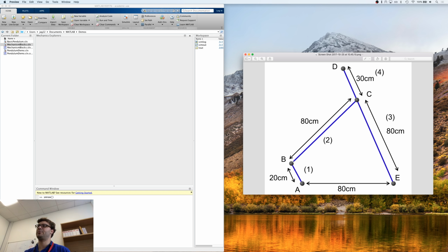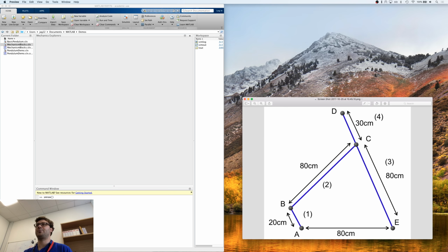So what I'd recommend is, once we follow this demo, you want to be able to make your mechanism of your convertible roof, with all the beams in the right configuration and places. Look at creating your motor and gearbox feedback loop using a single mass and pendulum. Once you've got that feedback loop and you're happy with it, you will then be able to import that and add that to your mechanism system. It's good to try and keep them separate until you're happy with both, and then bring them together at the end. Okay, so we're going to start completely afresh with this.